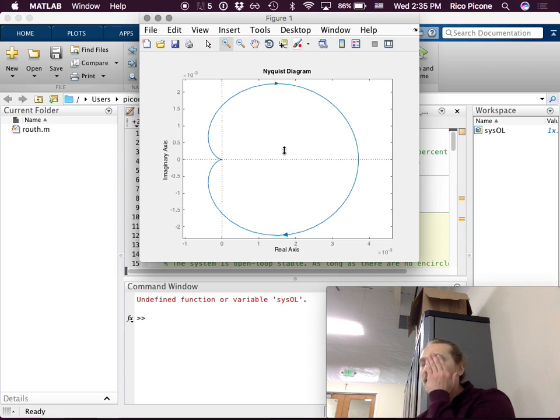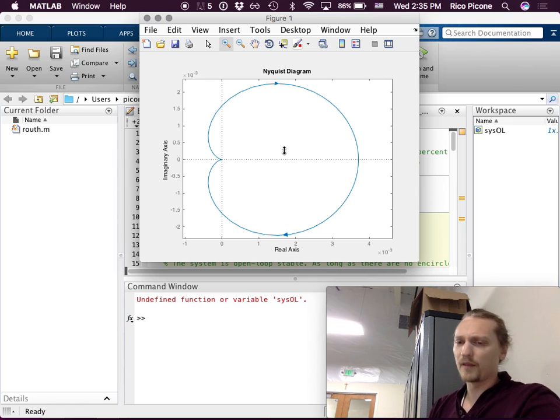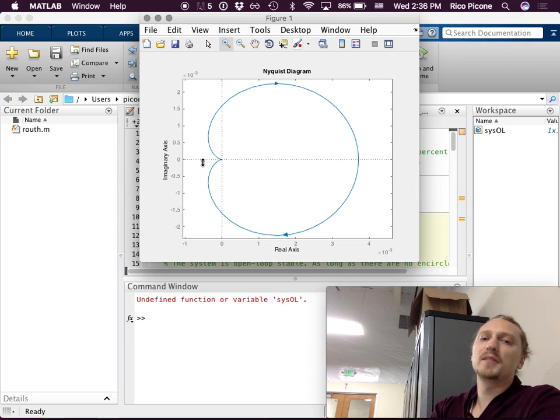So let's think in terms of, so we're going to be using the phase margin, but since we're still getting used to Nyquist diagrams, let's talk about phase margin and gain margin here. Did you guys remember the definitions in terms of the Nyquist plot? The magnitude at which it crosses that arc and then the angle that is. Yeah, so the gain margin depends on the distance between the real axis crossing, hopefully single real axis crossing, and -1. So the negative real axis crossing and -1, not this positive real axis.